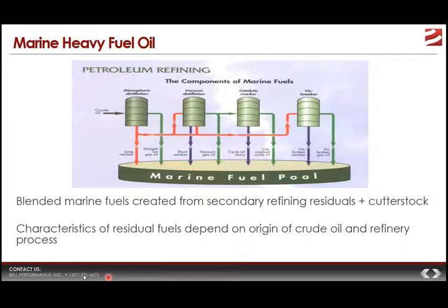You can take crude oil that comes from Saudi Arabia that's considered what they call light sweet crude, and you compare that to crude oil that's coming out of the North Sea or crude oil that's coming from, let's say, Venezuela, and they can look absolutely completely different. And so they have different properties, they have different components, and so the properties and the makeup of the crude oil very much influences some of the properties of the marine fuel oil. And then, of course, another thing that influences the characteristics of the residual marine fuel oil are the kinds of refinery processes that are employed to make it.